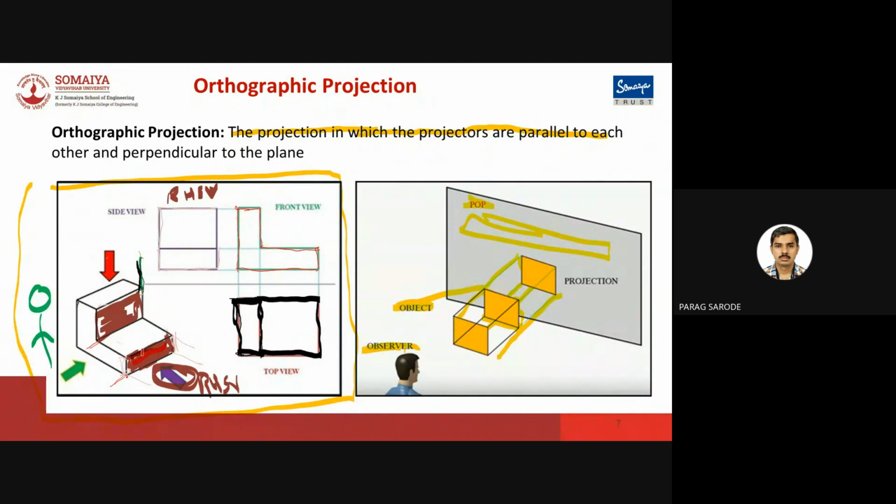So what we see in the right hand side is a rectangular block, whose width is this much. Now, this width of the right hand side view will be the same as the width that we get in the top view. For plotting the side view, we will project the projection lines like this. These are some of the projection lines, and this is the projection line we get from the top of the front.